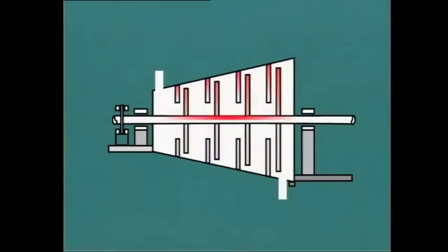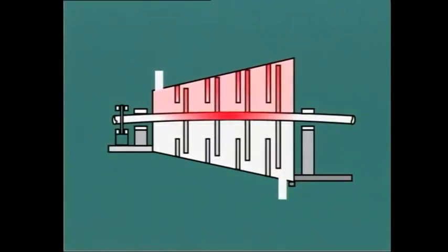However, there is another more vital reason for keeping the unit turning over when it is taken off load. Remember that the internals of the turbine are extremely hot. If we were to leave the rotor stationary immediately after shutting the machine down, experience shows that as the heat rises to the upper part of the rotor, it causes uneven expansion and distortion like this. This is known as hogging, and in some cases the bend may be so severe that the rotor will not recover its original profile even after cooling.